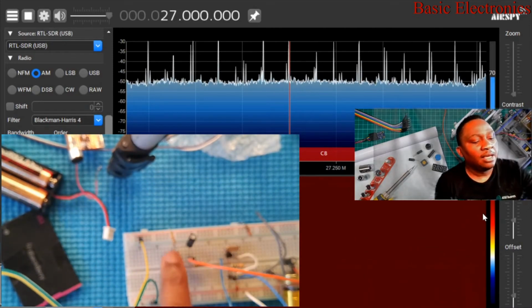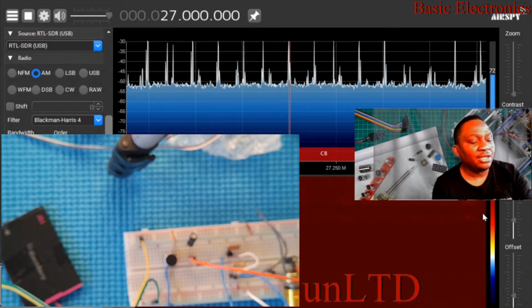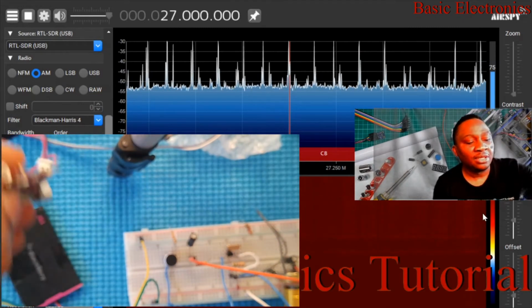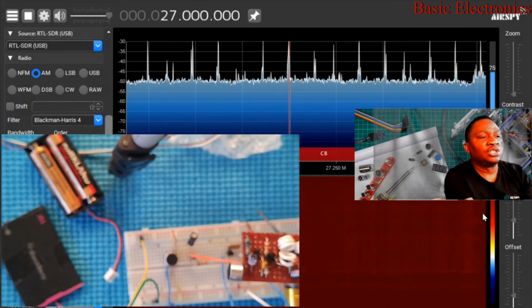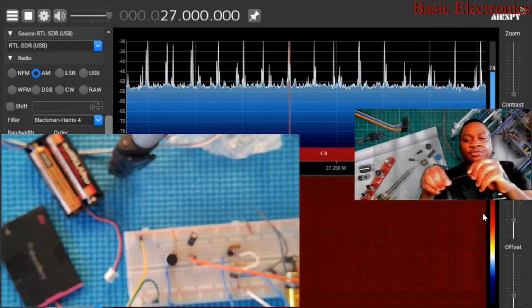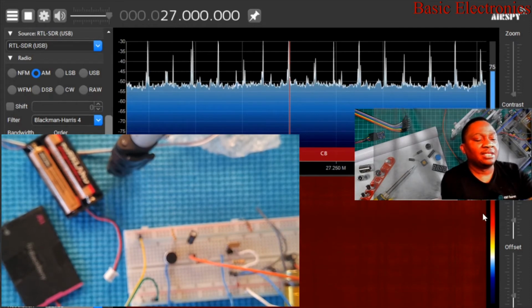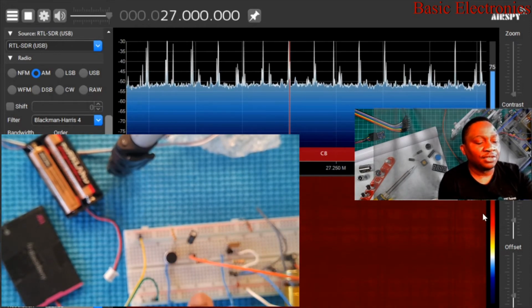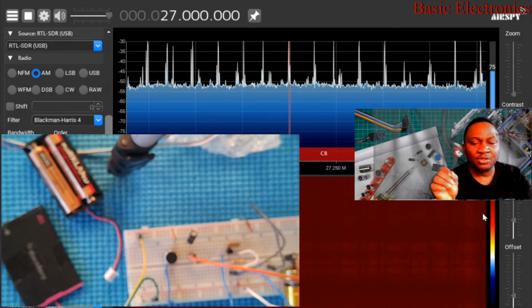And then it can also work with 1.5 volts. Very stable system right here. The frequency is stable, versus the previous transmitter we built, which is voltage controlled. So the frequency depends on the voltage. But the one we have today, the frequency depends on the crystal. So as the voltage falls for this new system, the frequency is stable. For the other system, the voltage fluctuates.